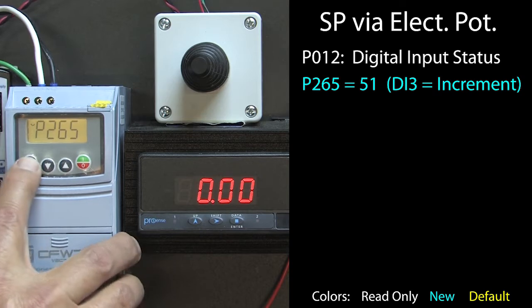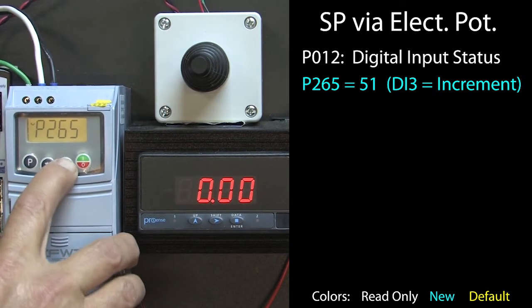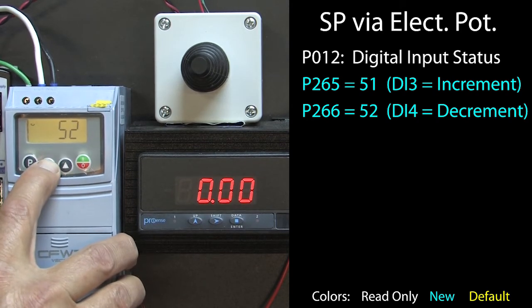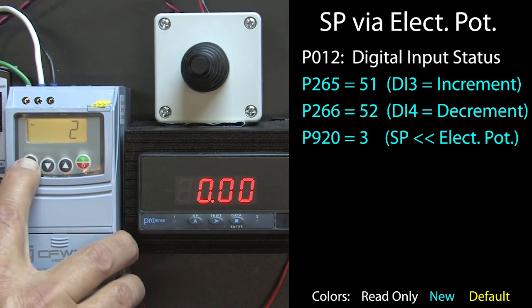Parameter 265 is where we tell the digital input 3 it'll increment the potentiometer, and parameter 266 is where we tell the digital input 4 it'll decrement the electronic potentiometer. Of course, we need to go to parameter 920 and tell the PID application to use the electronic potentiometer for the set point.